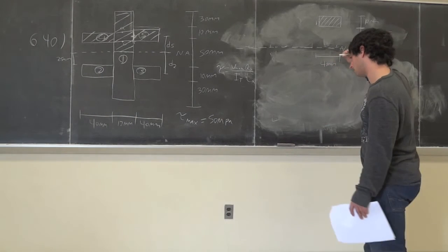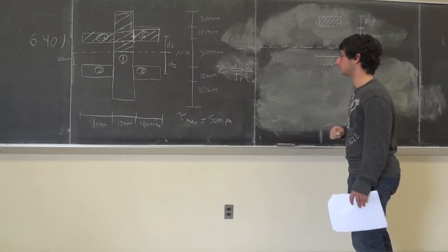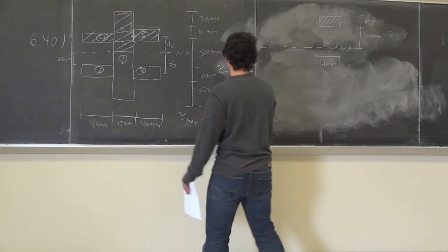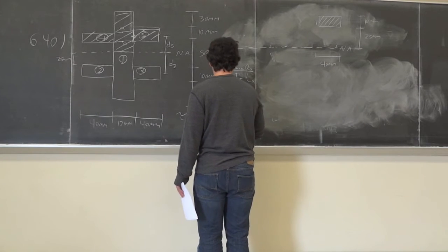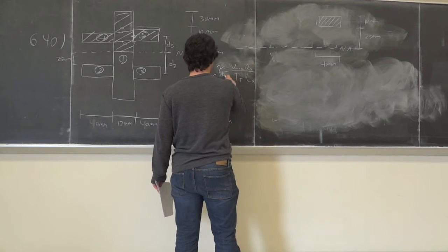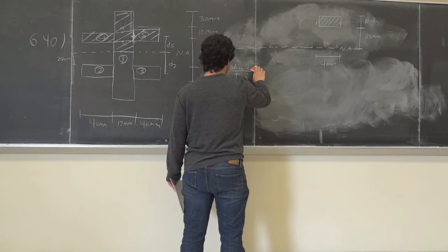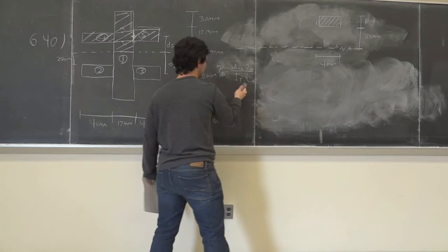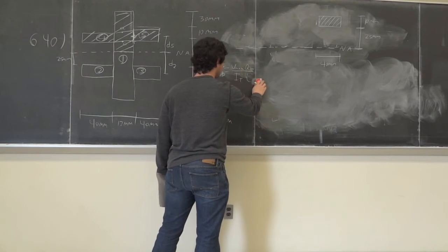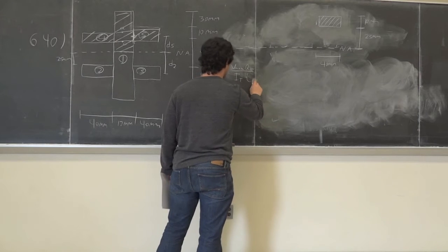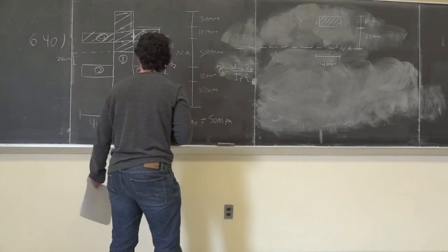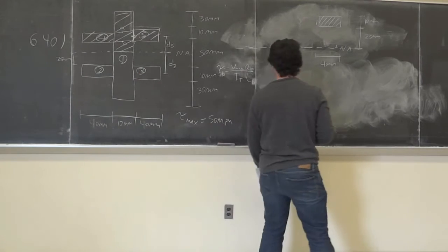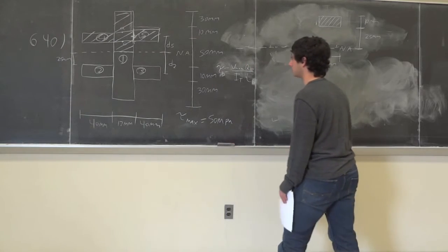Okay. So now we want to calculate the transverse shear in section B. So now our formula is tau B is equal to V max QB over the total moment of inertia, which stays the same, and the thickness now is TB. We discussed before TB is equal to 10 millimeters.